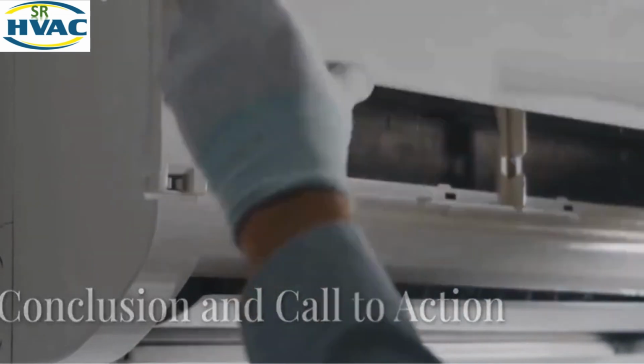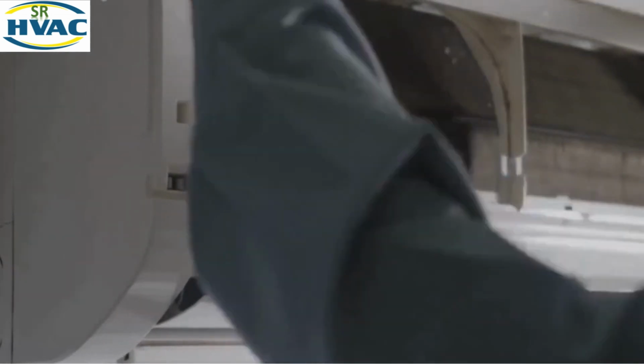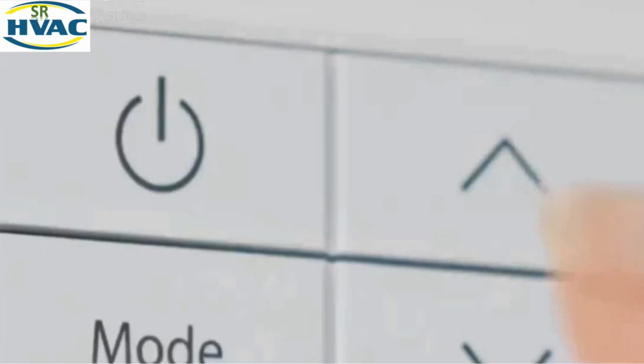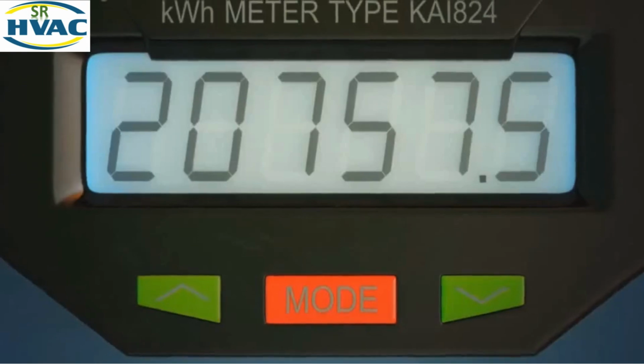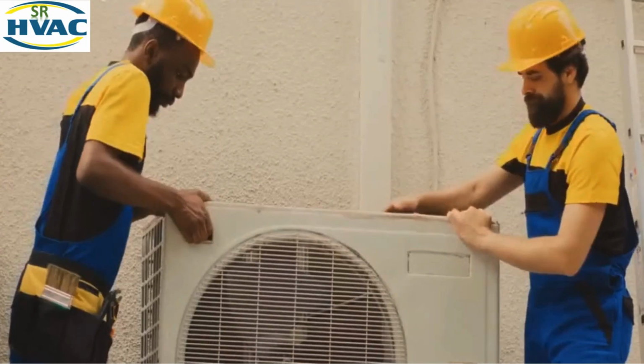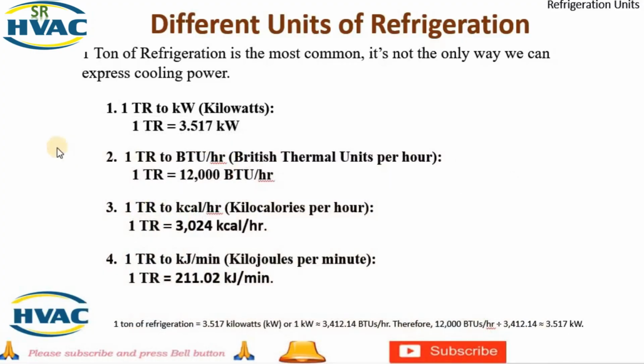To wrap it up, 1 ton of refrigeration is a unit that represents the cooling power needed to freeze 1 ton of water in 24 hours. It's equal to 12,000 BTUs, or about 3.517 kilowatts. We also have other units like joules and calories that express cooling energy in different contexts. Remember, understanding these units is crucial for sizing air conditioning systems, refrigerators, and industrial cooling units. So next time you're choosing an air conditioner or working on a refrigeration project, you'll know exactly what these units mean and how to convert them.